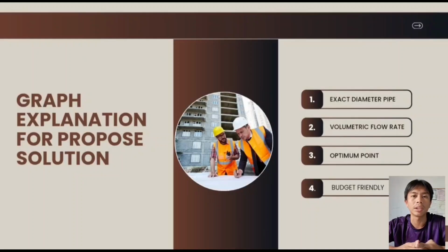So based on everything me and my group have discussed and calculated, we came up with a new design for the pipe network to ensure the system is safe and sufficient to be used. For the pipe size, we have adjusted the values aligned with the pipe system. The main pipe is enlarged to reduce the major losses, while the diameter of the pipe nozzle is smaller to make enough pressure to disperse the water through the nozzle. We avoid over-designing the pipe to reduce cost while making the pipe system work.